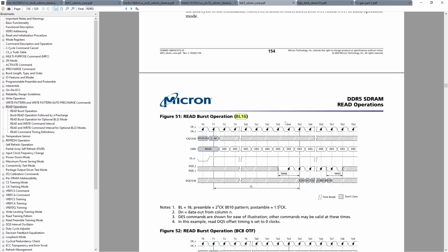but it does mean that you have good memory bandwidth if you're reading large amounts of data that happen to be sequential inside the memory, right? So if you're reading an image from the memory into the CPU or something like that, the long burst length is actually beneficial in that scenario. It provides extra bandwidth. But there's a compromise that needs to be struck between having good memory bandwidth and reading way more stuff than what you actually wanted on smaller read operations.